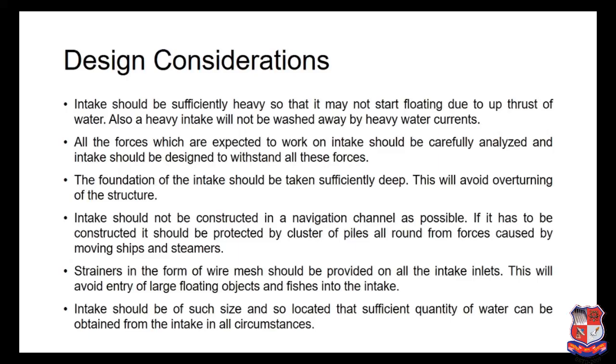And the foundation of the intake should be taken sufficiently deep, right? If it is not taken sufficiently deep, then this intake may overturn. So to avoid overturning of the structure, sufficient depth of the foundation should be provided.